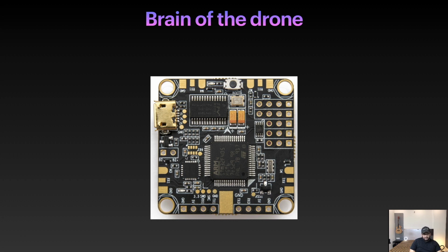But these days, flight controllers are getting a lot of advancement, and because of that, they are getting more and more elite day by day. So as you can see, this is another big chip here. This is nothing but an OSD, which sits between the camera and video transmitter, and it overlays a screen of information like your current battery or your current ampere usage. But we'll talk about that in some future classes when we talk about FPV.